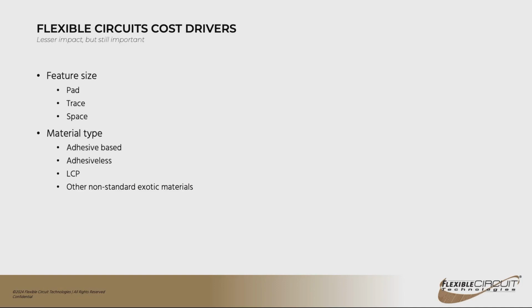Your material type can have an impact on the overall cost of the circuit. Adhesive based versus adhesiveless. The cost is not nearly as much as it used to be. It used to be a significant delta, but now those are pretty close, and so we use adhesiveless on a lot of parts, even though it's not probably as critical.